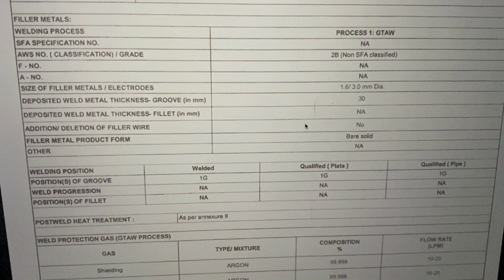In the fillet it becomes more important, because the plate thickness can vary from 5 millimeters to 100 millimeters, and the fillet could be a throat of 5 millimeters, or 10, or 20. So both are required to be listed down, because that becomes a good document to review subsequently when we want to use the same WPS with another set of groove parameters, to check whether we are very close and nearby to our requirements.